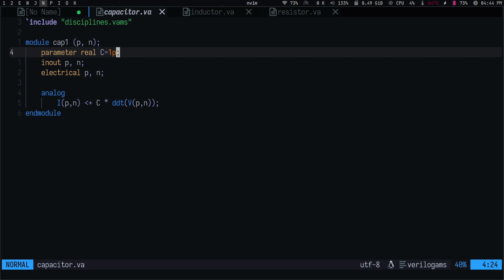Instead of wasting a lot of time building several different versions of the amplifier with different input dynamic range, output dynamic range, gain, or whatever, you write a Verilog-A file of an operational amplifier that models most of the behaviors you're interested in, and then you can play with that file. Later on, after you are satisfied with the result of your design, you start replacing your Verilog-A files with actual models, with actual SPICE stuff.